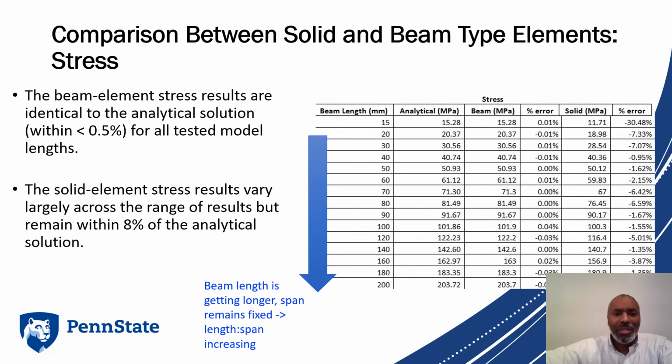So the beam element stress results are identical to the analytical solution pretty much for all the tested model lengths, and the solid element stress results vary largely across the range, but they remain within about 8% of the analytical solution.